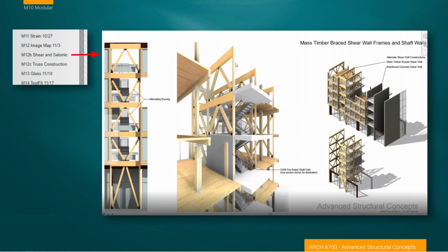In this case, what makes it an interesting project is this is an adaptable component. So if you stretch the module taller, the bracing will stretch with it. If you make these modules wider, they also will adapt. So you're making a useful parametric component.